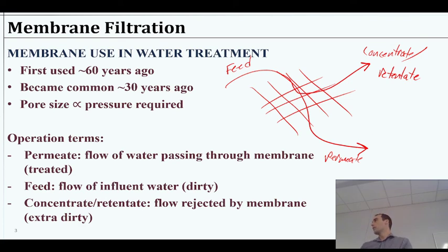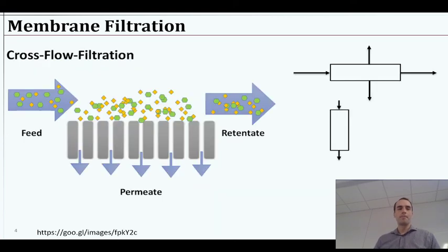That's not what they need it for. You might lose a little flavor or something, so I'm sure they try to control it, maybe use the right kind of membrane to retain all that. But then you squeeze basically all this water out of it, concentrate it up, ship it across the country, and then reconstitute it with pure water. And then you've got presumably the same stuff you started with. It just costs a lot less to ship, right? So that's pretty much the whole reason you do that, concentrate or from concentrate. Or maybe not, if you think that maybe you're losing some flavors in the permeate, which is possible. It would depend on their membrane selection and all that.